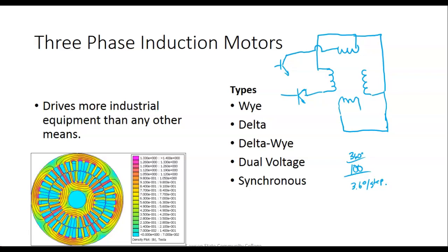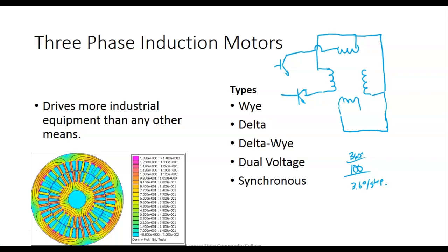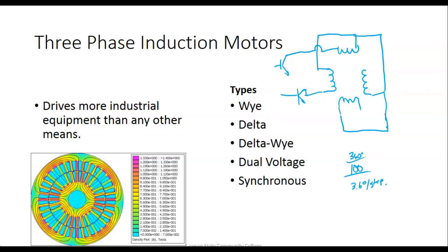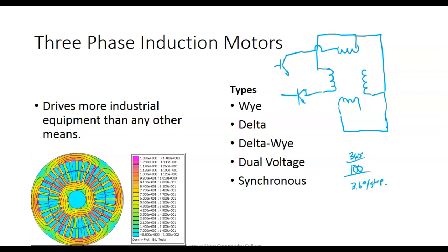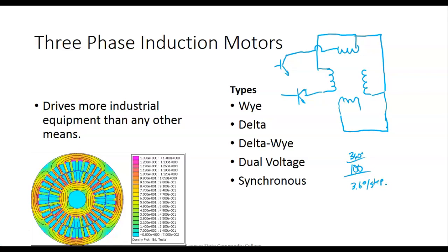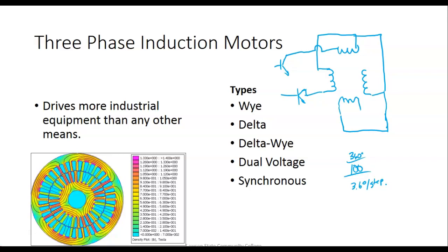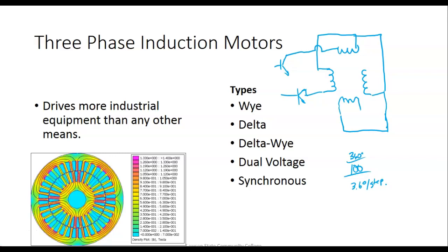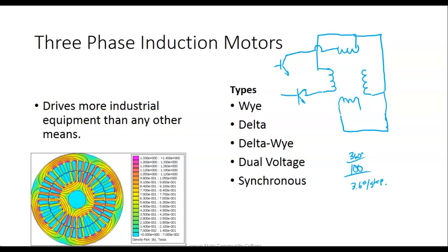You can hear it on a robot a lot because the motors will sing at you. So if the motors sing, that's probably a stepping motor doing that. I'm not saying it is, but it's a high probability that you hear the motor singing. What's nice about most stepping motors is we can run these without feedback, so we can run them open loop. But we have to start them from a reference point.